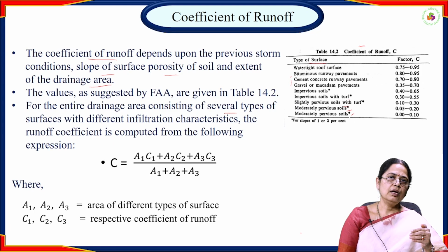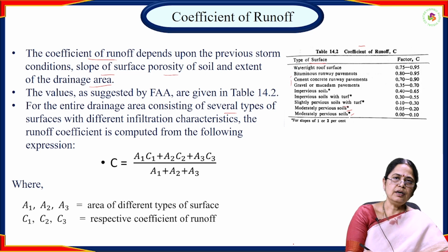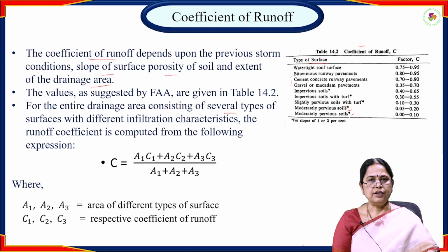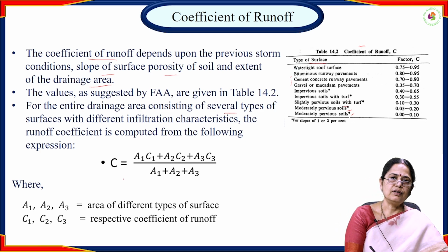Considering all the different areas from the runway pavement to the drainage inlet, we calculate one coefficient of runoff for the total drainage area.